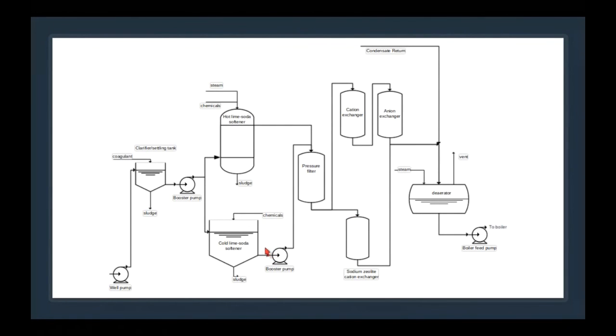Now, what have we just covered? Oh, so this is just a really kind of crude overview, but we got a raw water pump here. And maybe it's pumping from a lake or a river, or maybe it's coming from a well. This is going to be our makeup water. And depends what's in it. Maybe if we've got dissolved solids, suspended matter, we're going to have a clarifier settling tank. If we've got dissolved iron, we'll also have an aerator.